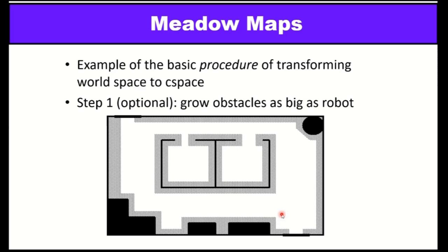Now how is it done? There are transforms, which are 3D transforms, which will show the obstacles as big as a robot, so that we can see that the walls and obstacles are grown to a higher height. So the robot's view now sees those grown obstacles, and the robot knows where the obstacle is and where the space is.